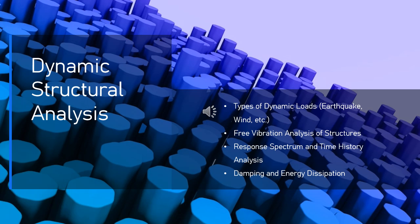Types of damping. 1. Viscous damping. In this type of damping, the force resisting motion is proportional to the velocity of the vibrating object. The damping force is typically expressed as Fd equals cv, where Fd is the damping force, c is the damping coefficient, and v is the velocity.